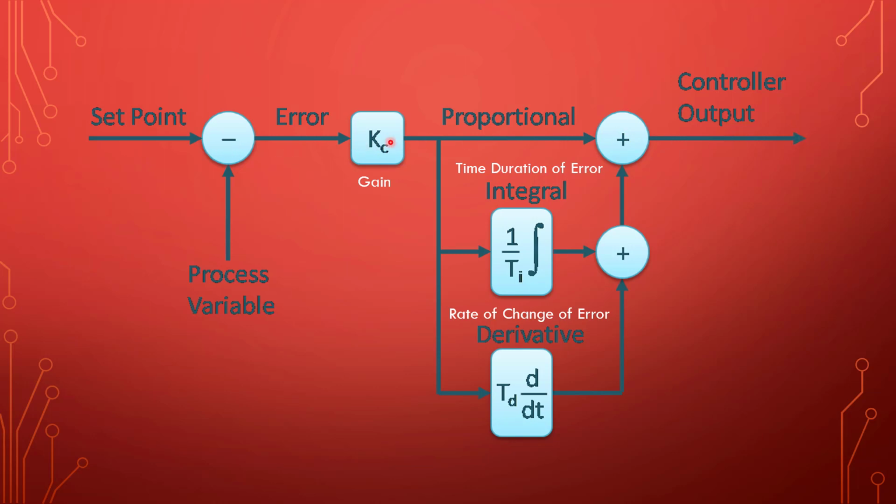If this particular type, this straight through type of control, is inadequate to give you the tolerances that you're desiring, the next step up is an integral controller. Because in a proportional controller, even though you have a set point and even though you have this process variable, it will never quite catch back up to the set point.